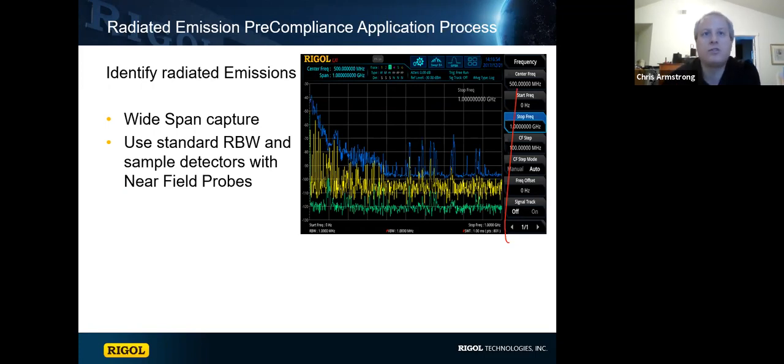And that really always starts with, again, a broad scan like this, where you're looking at peak detectors and holds, long-term max hold. I often use near field probes or a small antenna array, and typically I would use a near field enclosure of some kind, so a TEM cell, something like that. So there are different ways to look at products depending on what you're looking at. But in the end, start with this and look for signals that might be of interest.